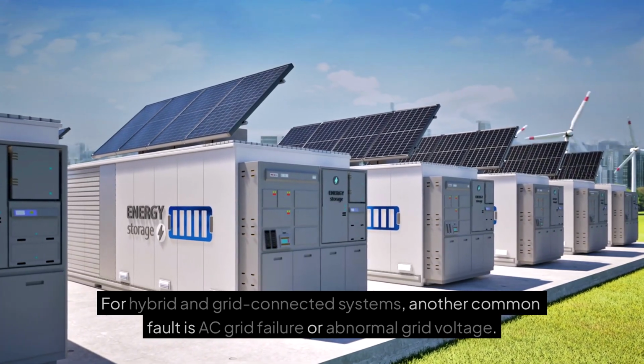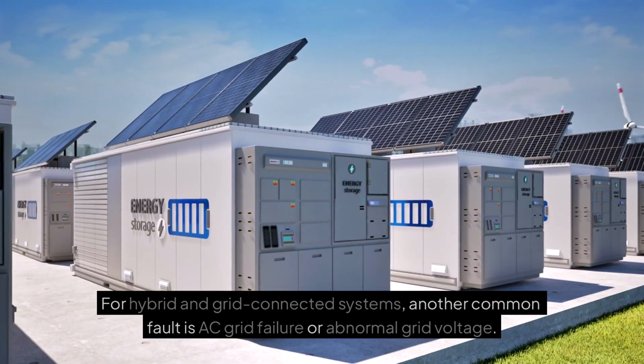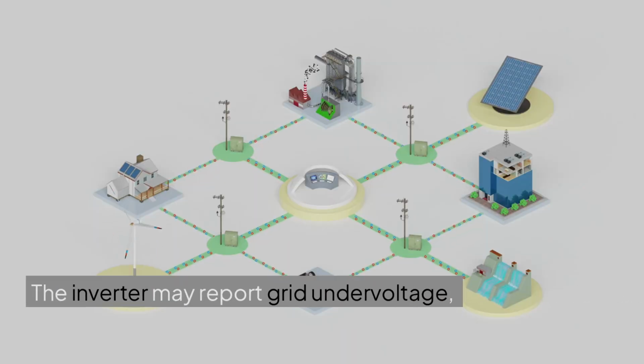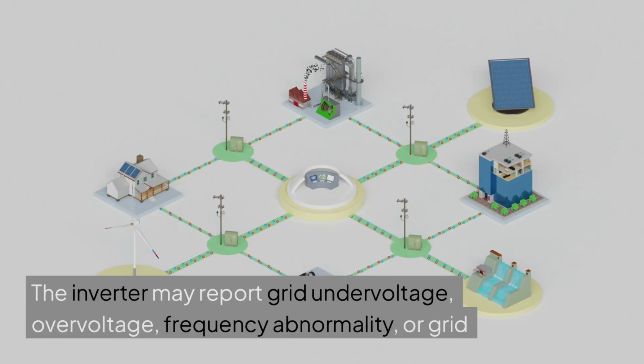6. Grid AC input fault. For hybrid and grid-connected systems, another common fault is AC grid failure or abnormal grid voltage. The inverter may report grid undervoltage, overvoltage, frequency abnormality, or grid loss.